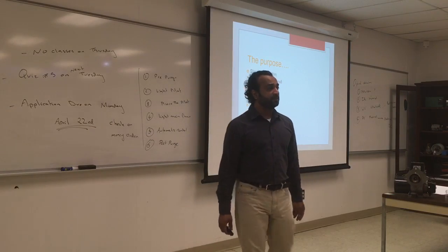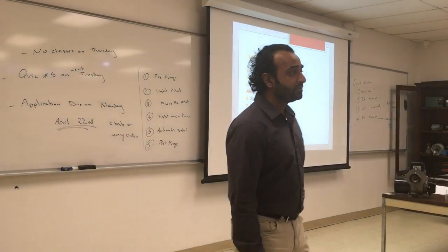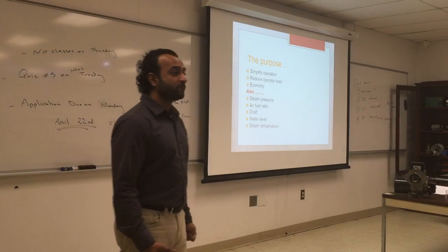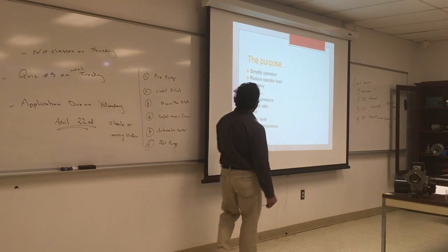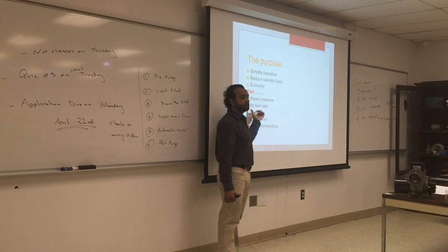We want to gauge the steam pressure because you don't want to have excess pressure. The more pressure you have, the more strain you'll have on the system, especially if it was not ready for it. And you also want to control the air-fuel ratio.